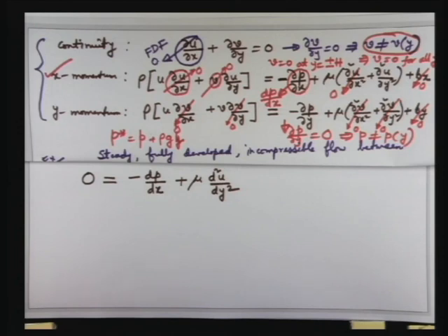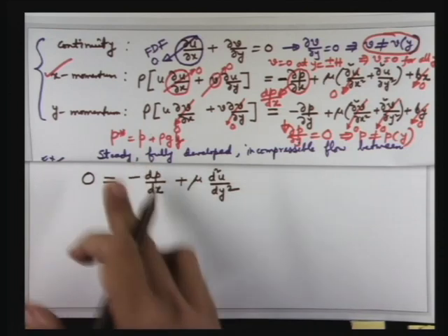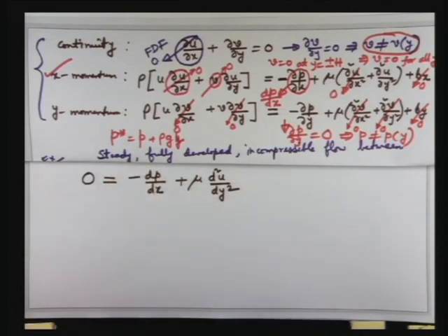So what have we achieved by this simplification? We have achieved one important thing. We have converted the non-linear form of the Navier-Stokes equation to a linear form, because the left hand side, which gave rise to non-linearity, has become 0 because of the simplification. So fully developed flow means that the left hand side is identically 0, and that makes the Navier-Stokes equation perfectly linear. So then let us try to solve this equation.